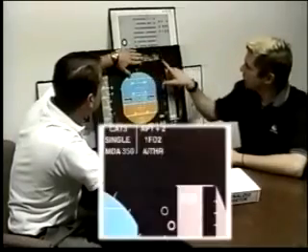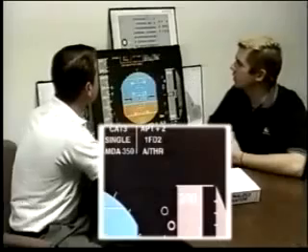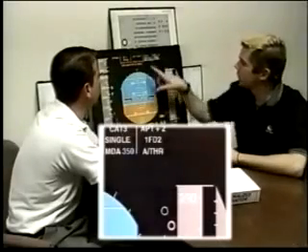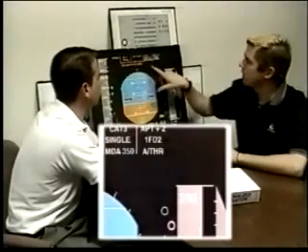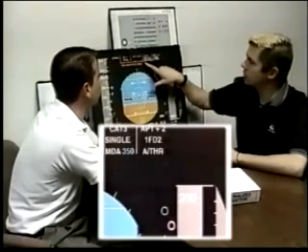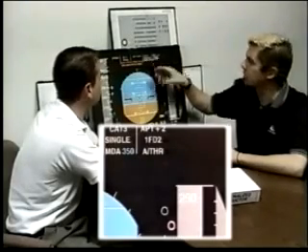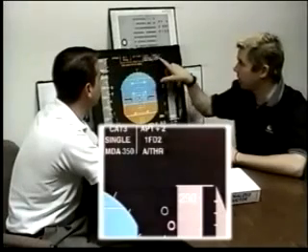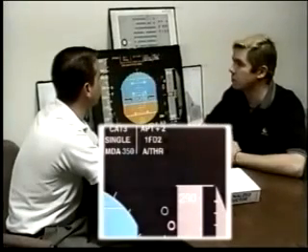Can you go into detail on the last two columns? Yeah, looking at this stuff, with a Cat 3 single, we could be going down as low as a Cat 2 approach. But when I see the MDA 350 in here, an MDA means a barometric reference, which is for a Cat 1 approach. Cat 2 would require a DH of something to be set in there. So with the autopilots coupled here, I'm guessing we're going to be doing a Cat 1 autoland.